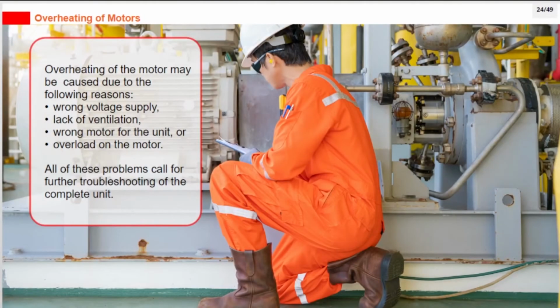Overheating of the motor may be caused by the following reasons: wrong voltage supply, lack of ventilation, wrong motor for the unit, or overload on the motor. All of these problems call for further troubleshooting of the complete unit.